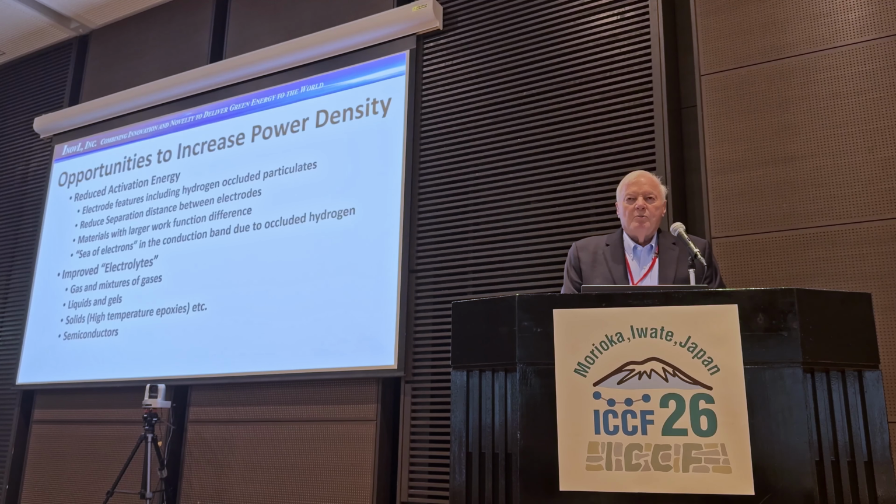It's amazing what will provide mobile ions when the temperature gets hot. And we were using high temperature epoxy for what we thought was an insulator early on, and then we discovered that it actually became an electrolyte at high temperature.